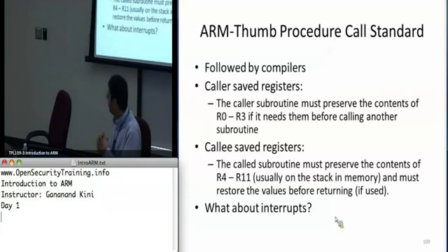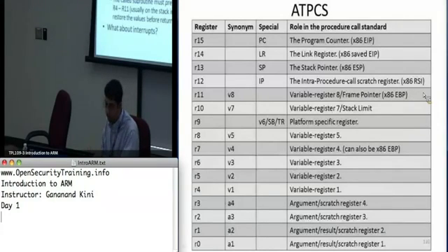So if user mode has R0 through R11, FIQ has a set of banked registers which go from like R4 through R10 maybe. Those registers can be used in the new mode without affecting the original mode's registers.